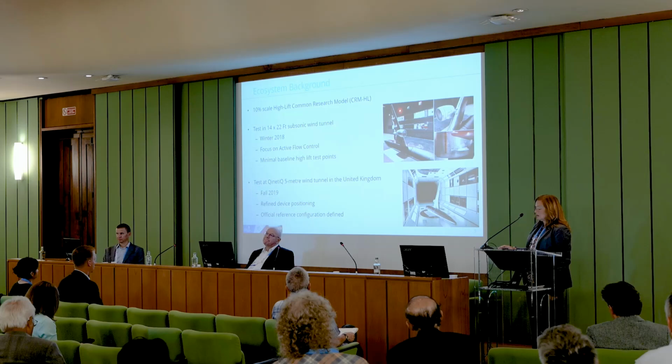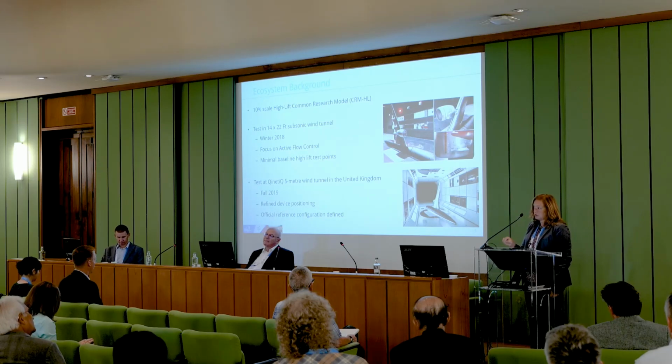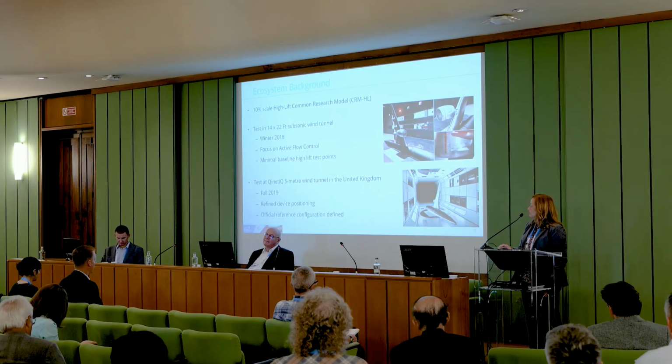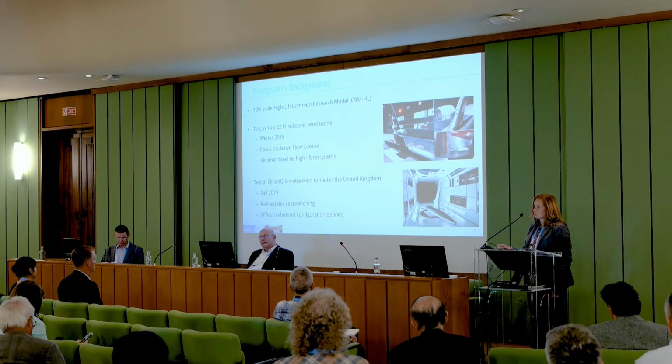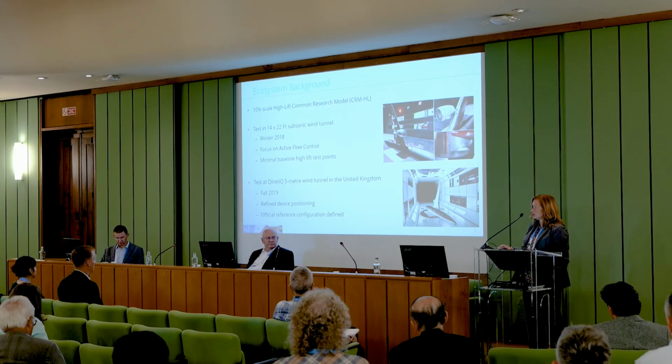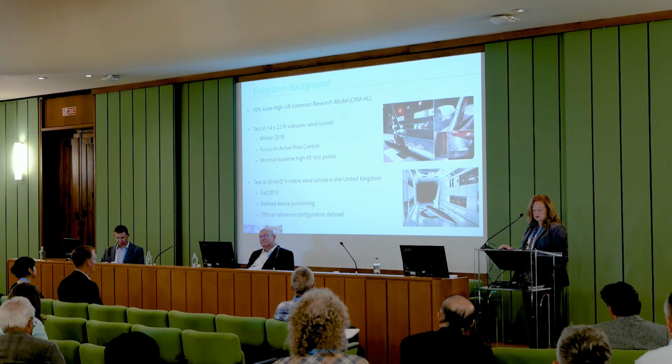Just a little bit of background. I think Adam and Jeff mentioned the 10% scale high-lift common research model. That model was built after the initial reference configuration was developed. It was tested in the 14 by 22 foot subsonic wind tunnel at NASA Langley in the winter of 2018. The focus of that test was active flow control, but toward the end of the test, we were able to get some conventional high-lift data, about 3 days' worth, some test points that we could use.